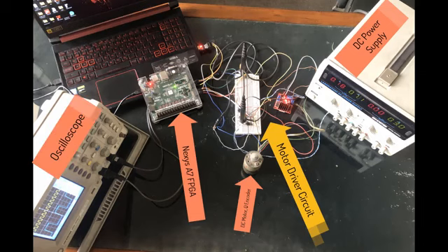An oscilloscope is used to observe two signals. One is the quadrature encoder pulses, which basically represents the speed of the motor, and the other is the PWM signal generated by the SoC. And a UART to USB converter is used to display the messages on the computer terminal which are generated by the SoC. So the way it works is that the CPU on our FPGA takes quadrature pulses and sets a reference speed of the motor by tuning the PWM signal. And when the input voltage of the motor changes to change its speed, the CPU adjusts the duty cycle of the PWM so that the reference speed of the motor remains intact.